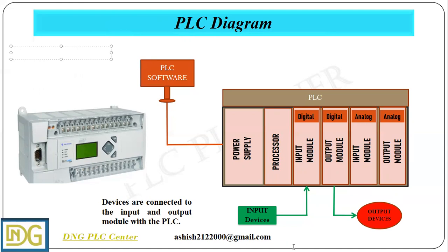So here, this is an Allen Bradley PLC, and as you can see, this is the display. These are the LEDs which show the error, program update and run, program run, download, and whether our inputs and outputs are on or off. We relate all these things to the LEDs.